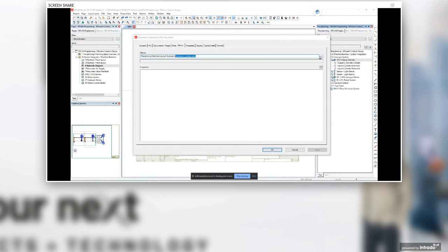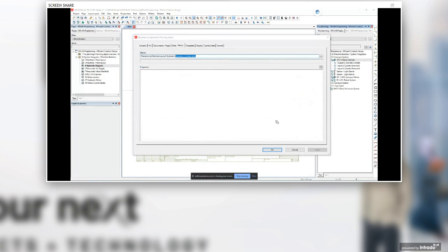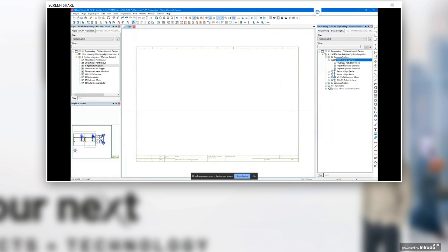And here we can see the specific layout of that cylinder, whether it's from a circuit diagram perspective or from a hydraulic perspective. Now that I've associated this, all I need to do is drag this cylinder onto my page, and there's my tank, there's my pump, and there are my 2 cylinder clamps closing that particular system together.